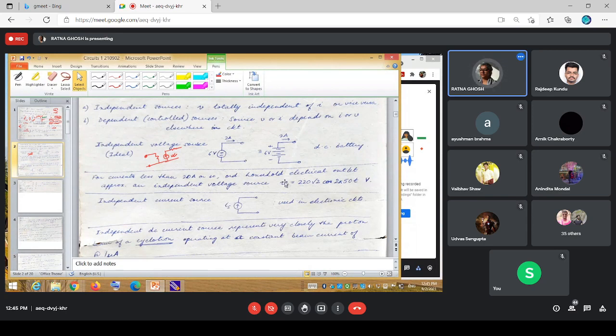As you know, fuses are attached to these outlets. If you have a high voltage, high amperage outlet, you would have a limit of say 10 amps typically. So the maximum you could draw instantaneously would be about 20 or so. For the other normal outlets, you would have 5 amp fuses connected, so that would be about 7.5 to 8 amperes max that you could pull instantaneously. Those are the ranges, but it can be treated as an independent voltage source.